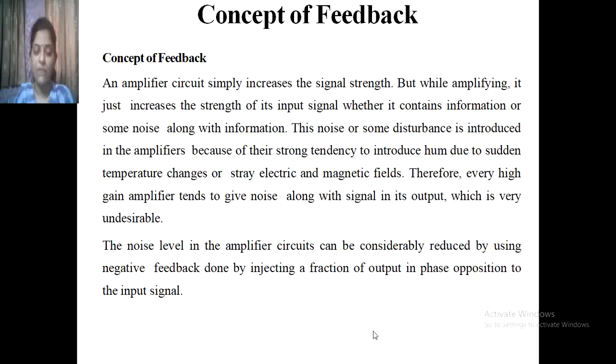The noise level in the amplifier circuit can be considerably reduced by using negative feedback, done by injecting a fraction of the output in phase opposition to the input signal. So you will get the idea of the concept of feedback.